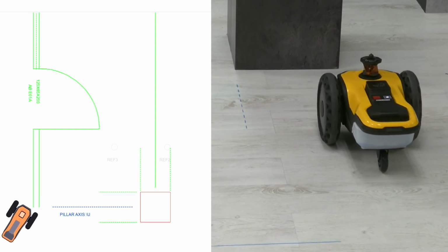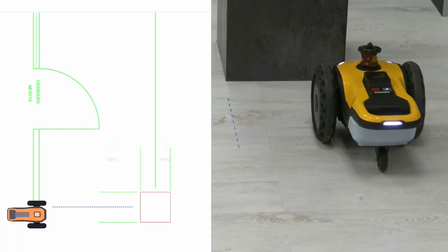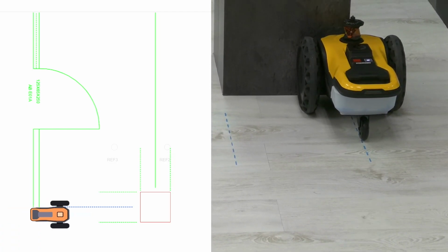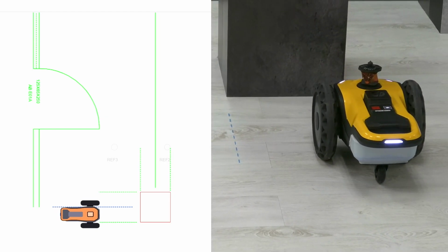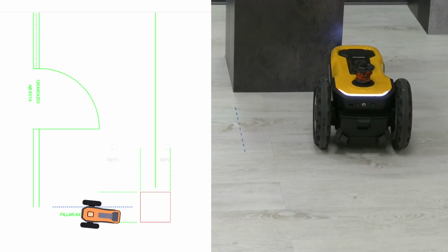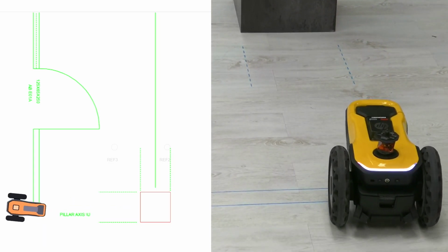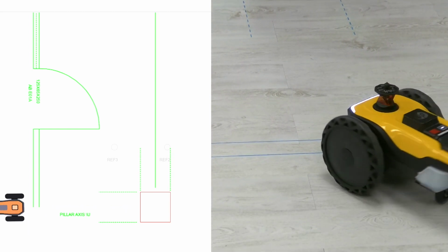As I mentioned earlier, SitePrint has obstacle avoidance capabilities to provide worry-free operation by just one user. It can avoid obstacles in 2 different ways. It will avoid all the obstacles that you loaded in the obstacle layer of the CAD file, but it's also equipped with cameras and cliff sensors that will detect any unknown obstacles to avoid collisions or fall-offs.